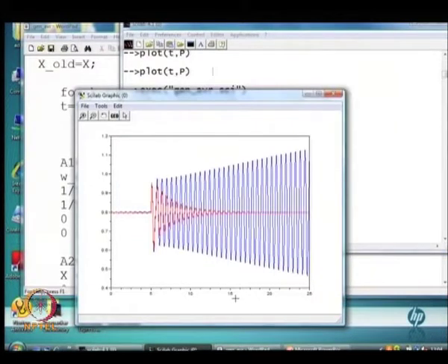Now, look at the red curve. You see that it damps out. The equilibrium point also does not change, because remember that the output of the power system stabilizer in steady state is 0. So, this particular stabilizer will introduce damping into the system and prevent this kind of instability, small disturbance instability.